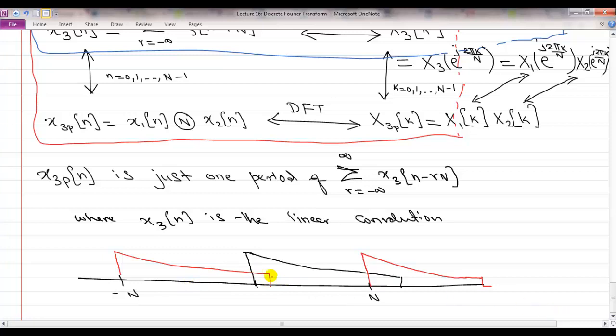And what you are going to see is whether or not you have this overlap. Whether this thing overlaps depends upon what n is in relation to the length of your linear convolution. So what is this endpoint? This is L plus p minus 1. We talked about linear convolution being of length L plus p minus 1. So when will these things overlap?